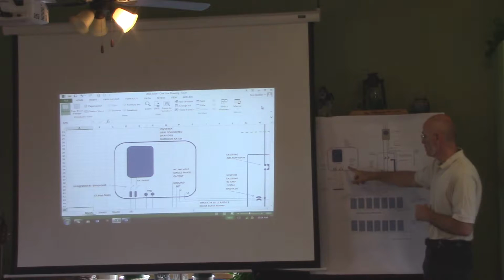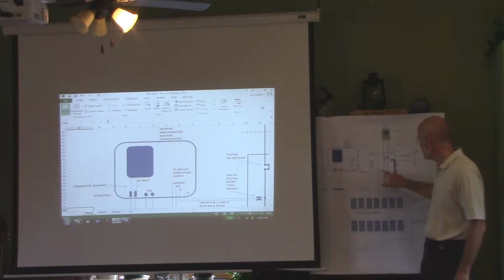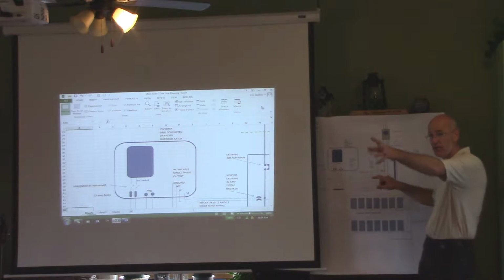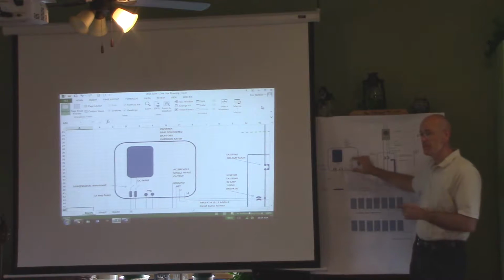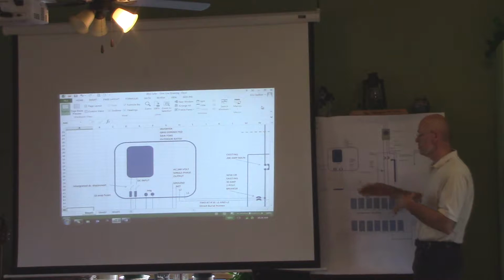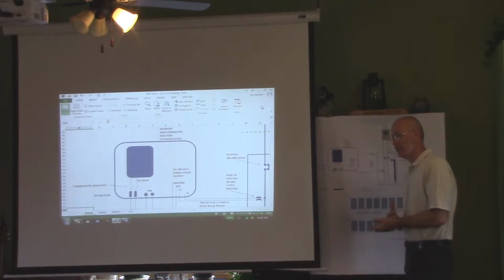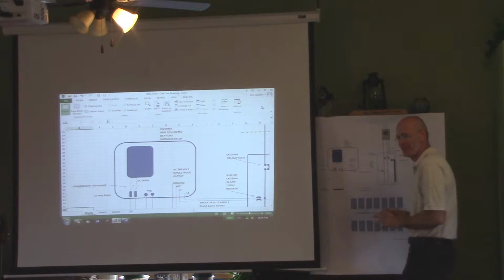But you need to understand what we're doing. We're going from DC to AC, and we're going to make 120 volts from here to ground and 120 volts from there to ground. So there's an L1 and an L2 on your drawing. One of these outlets in the room is connected to one of these wires off of a breaker in your house, and then maybe a different outlet somewhere is connected to the other leg. So you got 120 to ground on this leg and 120 to ground on that leg. Between the two, you got 240 volts. Okay, now I'm going to skip all the technicalities of that, but that's the voltage. You don't want to put your tongue on it. If you put your finger on it, you're going to feel it. It won't kill you usually. Let's put it that way.